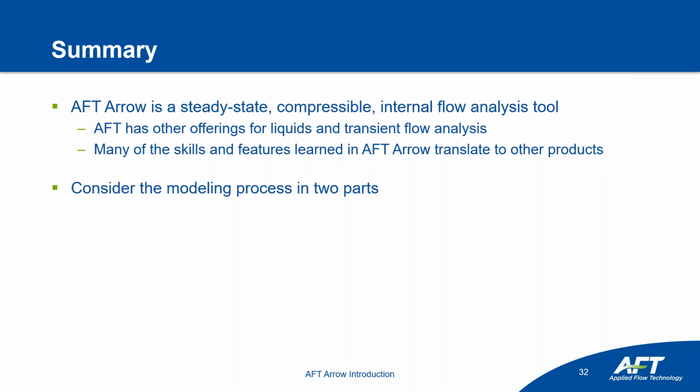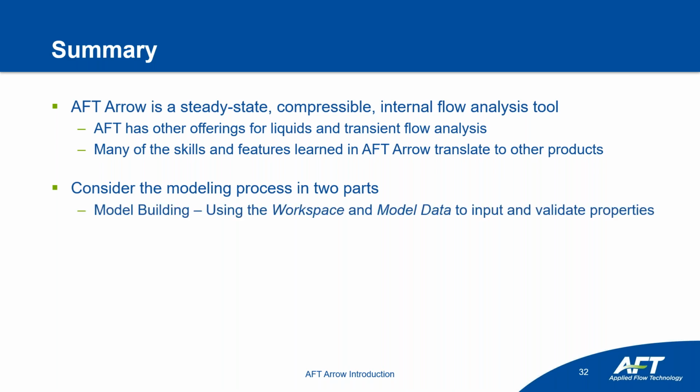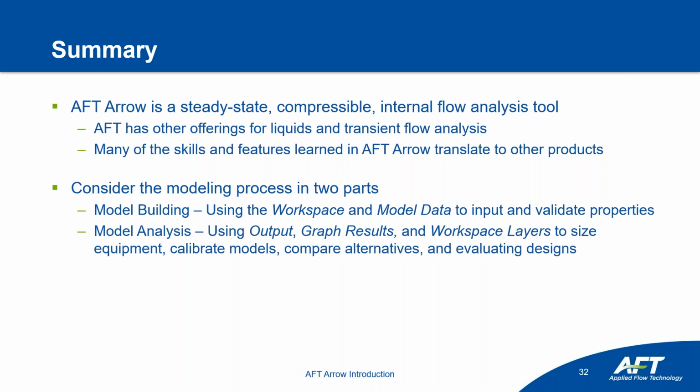Typically, you want to consider the modeling process in two parts. We saw model building using workspace and model data for our input and validating our specifications. Again, a common saying is garbage in equals garbage out, so your results are only as good as the information put into the model. The second piece was model analysis using output for tabular information, graph results for understanding how parameters might relate to one another, and then workspace layers to associate that output or input with the model itself.